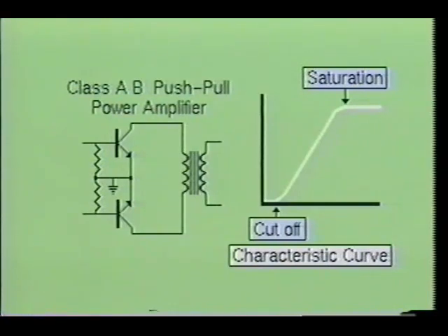There are two types of AB amplifiers, AB1 and AB2. The Class AB1 amplifier is biased a little more negative than the Class A operating point. In the Class AB2 amplifier, its operating point is biased even further negative than is the AB1. Normally, the AB2 bias point will be at the top of the lower knee of the characteristic curve. Since the AB2 is biased more negative than the AB1 operation, it requires more driving power than the AB1 amplifier.